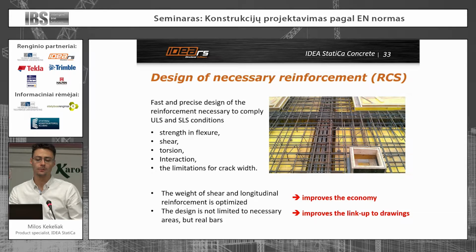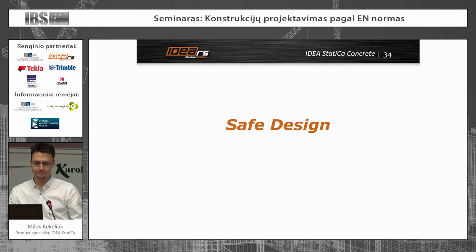They are presented in this slide, and this leads to reduced weight of reinforcement, both shear reinforcement and longitudinal reinforcement. And this design works not with necessary areas but with real bars, so it improves the economy as well. It improves the link to drawings, so the areas are not imaginary.